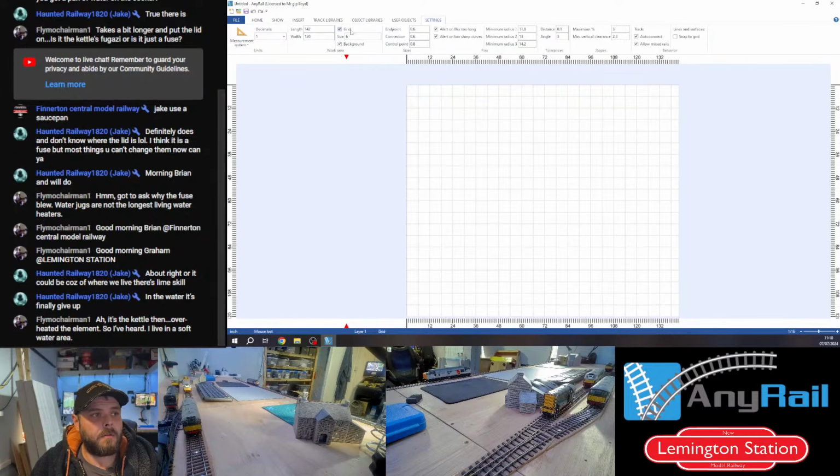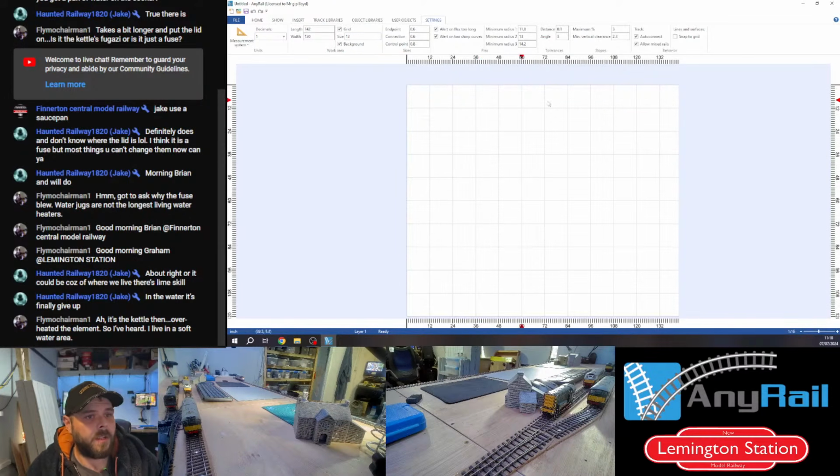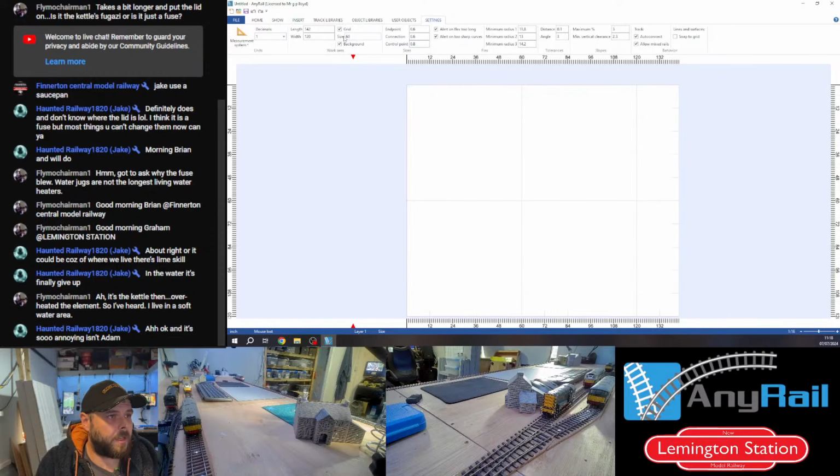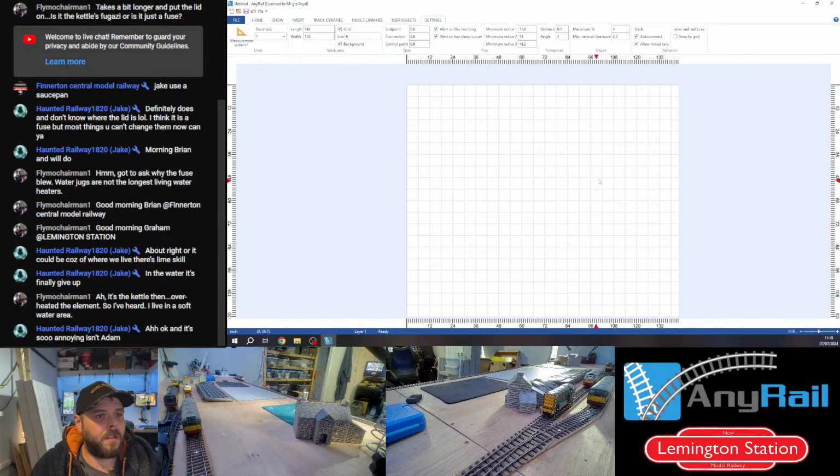You can tick this little box. This will give you a grid format out on your workspace. Underneath here there is a little number. In this number box here you can put in whatever size. So if you want, at the minute these are 6-inch squares, so if you wanted 1 foot squares you would put 12, and then that would give you your final workspace in grid points. I like to use 6-inch squares.